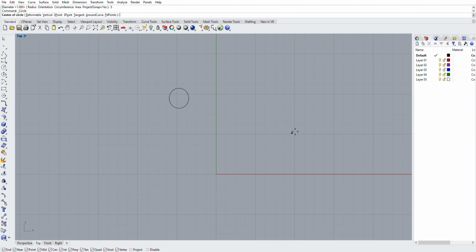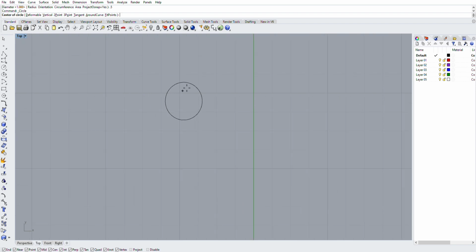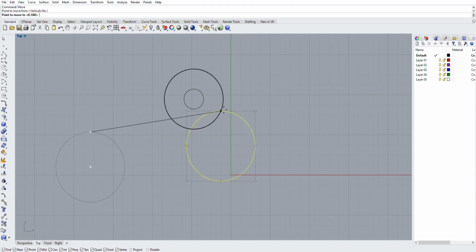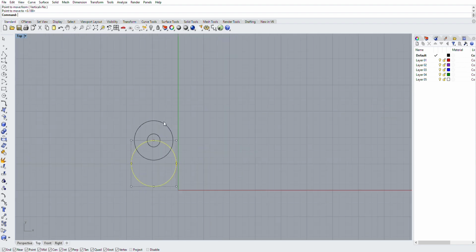So let's make another shock tab. This time, we're going to make one that sits on a tube. So same as we did last time, 1/2 inch bolt hole, 1.5 inch circle for where the bushing would sit. We're going to set a 1 3/4 inch tube to represent, say, a piece of DOM, a shock tube or shock hoop, something like that. And we're going to move that from the top of the circle to the center of the bolt hole, because our shock tab dimensions are always going to be from mounting surface to the center of the hole.